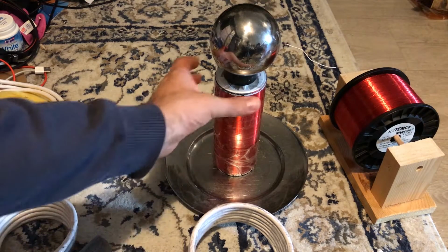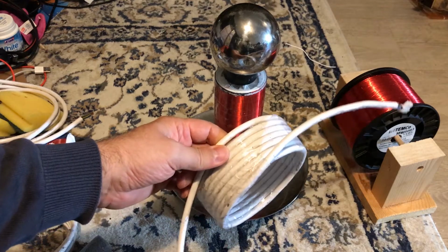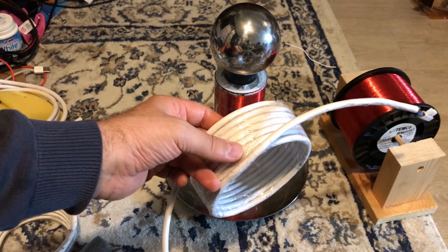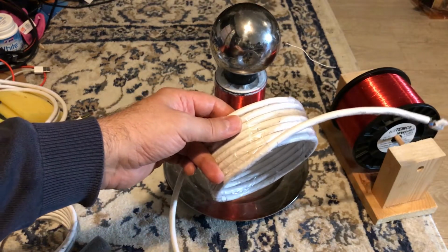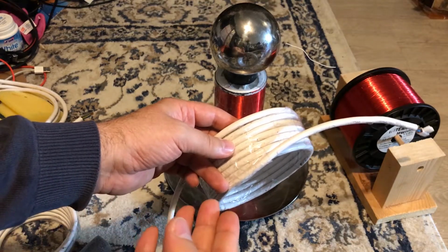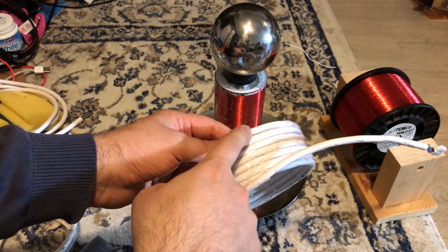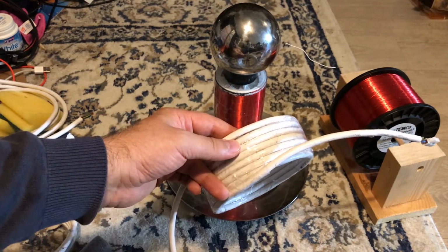Okay, so far we have made the secondary coil, and also we have made the primary coil. Now usually the primary coil is made of bare conductor. Copper pipe is a popular choice to make the primary coil. The reason is when you want to tune the primary circuit to the secondary circuit, you want to be able to change the number of turns on the primary, because that gives you flexibility to tune the circuit.